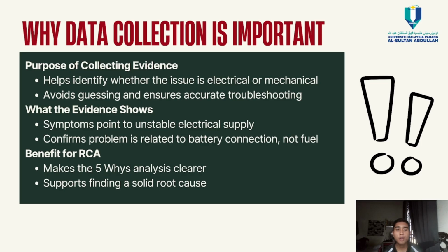The evidence shows that the symptoms point to unstable electrical supply. Not only that, it confirms that the problem is related to the battery connection, not fuel. And the benefit for RCA is that it makes the 5 Whys analysis clearer. Not only that, it supports finding a solid root cause.